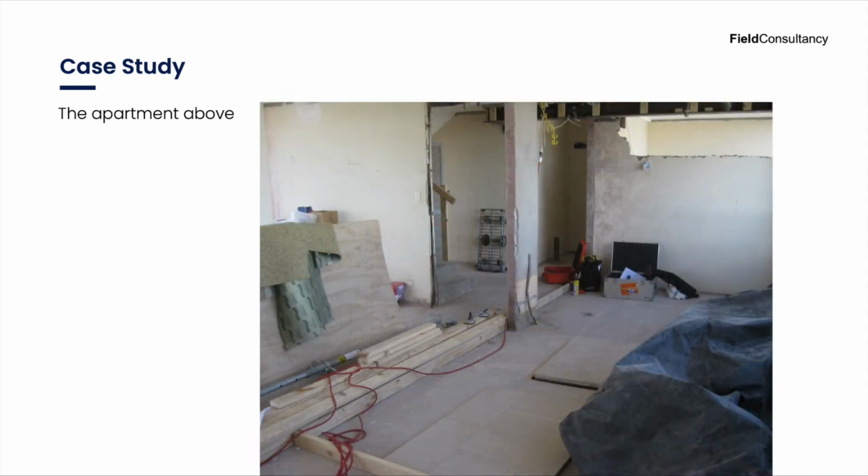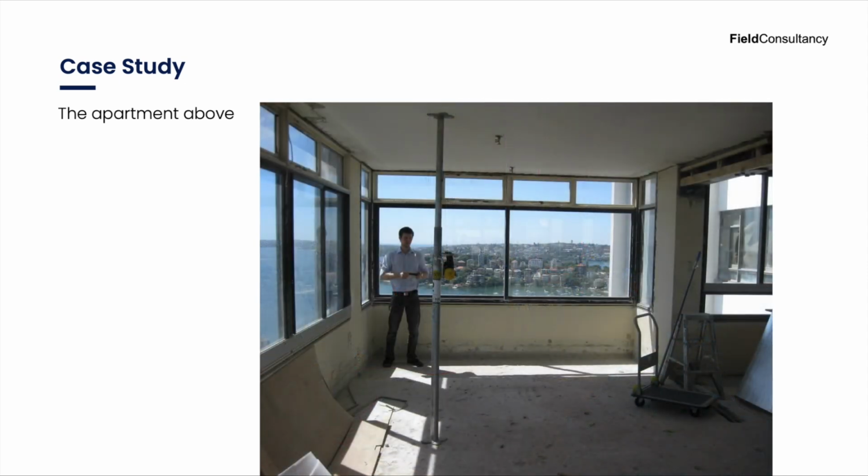Here's some photographs of the apartment above and some of the samples that we used. Here's two different tiled samples which had resilient materials as underlays to the tile surface to prevent impact noise transmission. Because the apartment was under renovation, we had the opportunity to do a lot of prototype testing before the final selections of the floor surfaces were chosen.